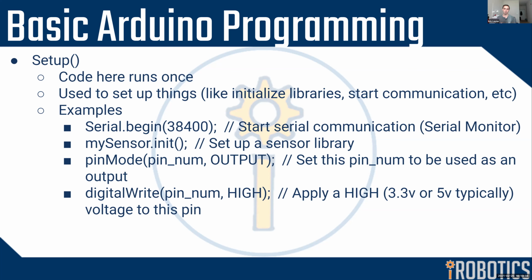You only use this pin mode function when you're actually driving a digital voltage line, like an enable pin, where you'd send out a 0 or a 1 voltage, not something where you'd send actual data over some sort of communication protocol. Does that make sense? Kind of went off on a bit of a tangent. Yeah, no, okay. Makes sense. Thanks.